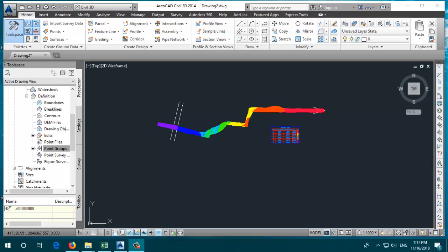I collect the points by total station, then sometimes I do it manually to make an additional check, and finally I have a GPS, so I made 6,000 points for this mountain to compute the volume. So in this lesson you will also compute the volume of this big mountain.